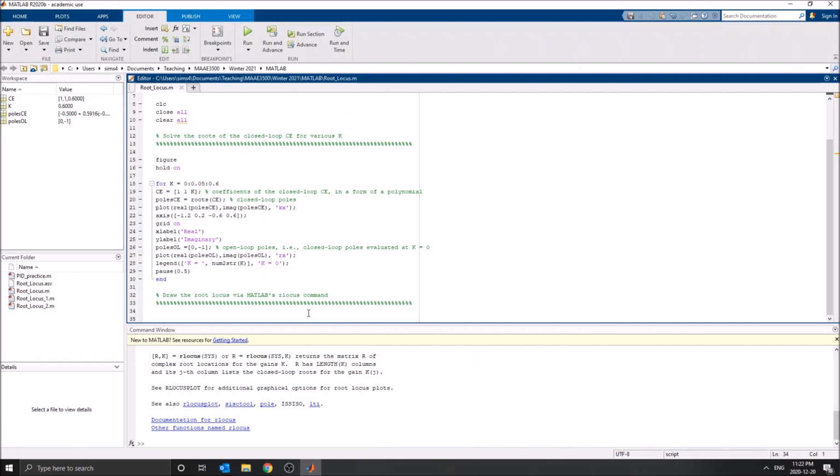Okay, so we're back to MATLAB. As we've seen on the whiteboard, using the rlocus command is not an issue at all, although the architectures are different. So let's use the rlocus command to draw the root locus for us. Let's see how easy it is. As we've discussed, all we need to specify is the plant transfer function G of P. And the way we do that in MATLAB is by specifying the numerator as a polynomial and then specifying the denominator as another polynomial.